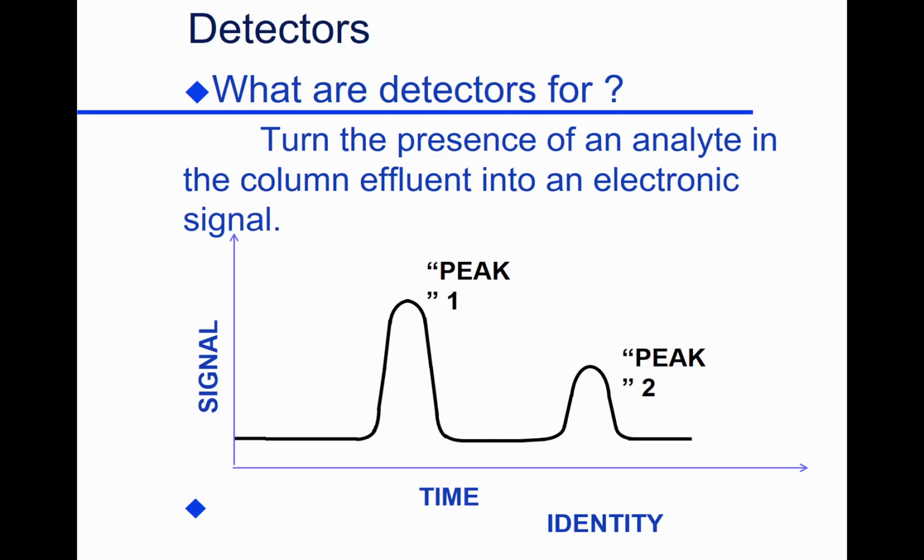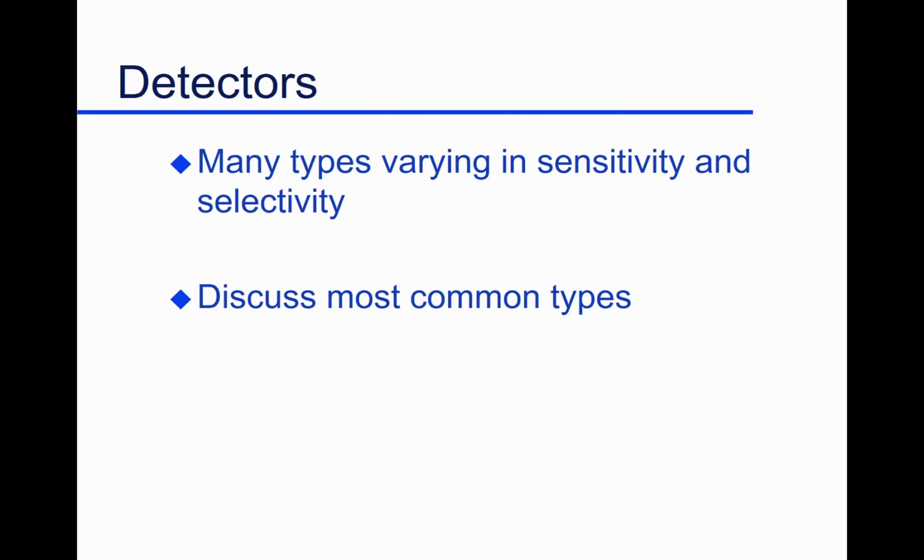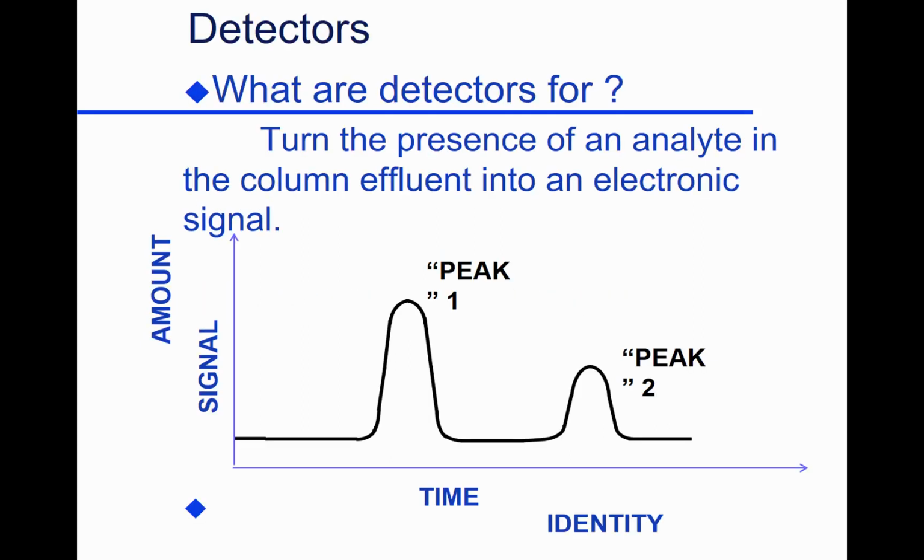But in gas chromatography, your peaks sometimes are broader, narrower. If they're broader, of course, they're shorter. If they're skinnier, they're taller for the same area. So we have to measure area in gas chromatography. We do area as well because the column changes efficiency, so the height is not always reliable.